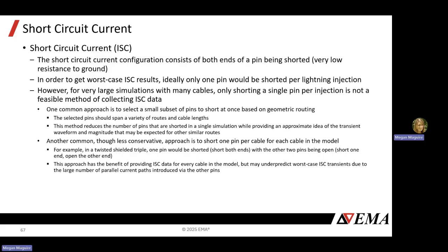But what you can do essentially is sometimes combine your short circuit current with your VOC simulations, or your open circuit voltage simulations. Say you're only shorting a few and you anticipate that that would have minimal impact on your open circuit voltages. So this is looking at ways to try to reduce the total number of simulations to run.